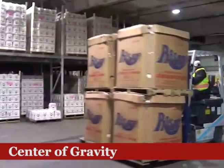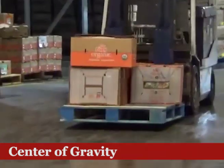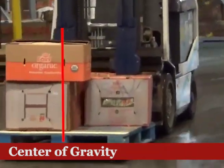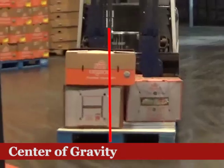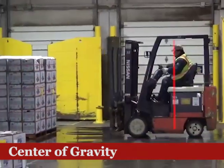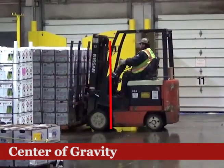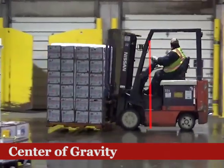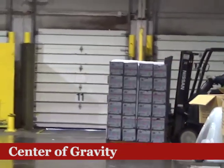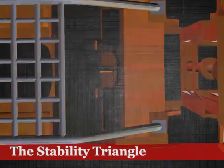In a perfectly symmetrical load, its center of gravity is in the middle. Most loads are not evenly distributed, so the center of gravity will be somewhere other than the middle of the load. When you lift the load, the vehicle and the load create a combined center of gravity, which is closer to the front of the forklift. It is this combined center of gravity that must remain inside the stability triangle.